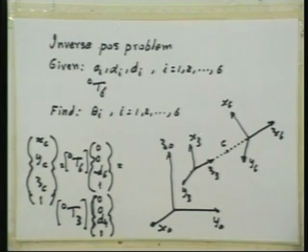So the solution of the inverse kinematics problem becomes very simple because of the existence of a concurrent wrist. If the wrist is not concurrent, we do not have these simple forms.